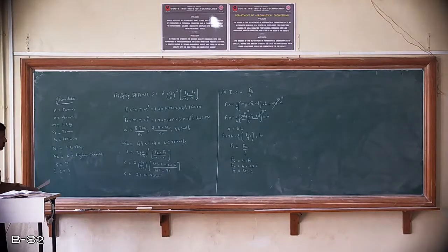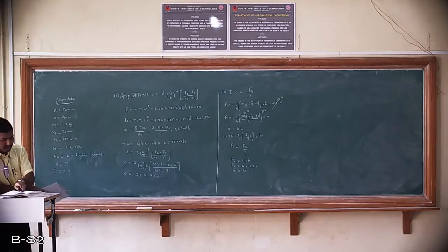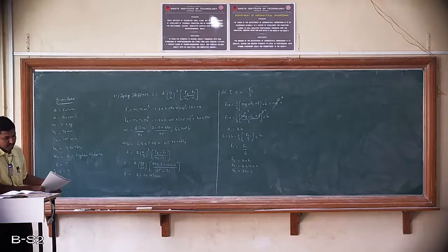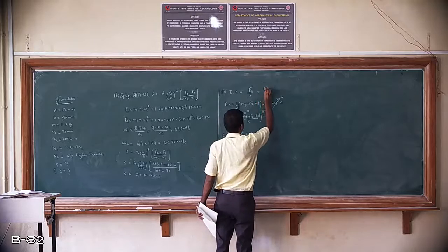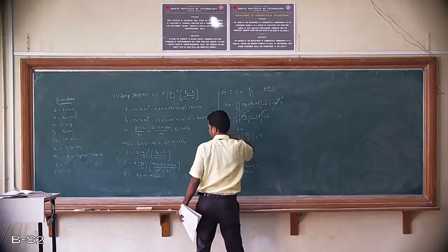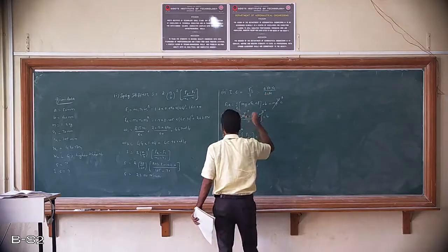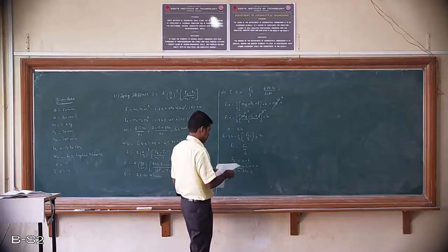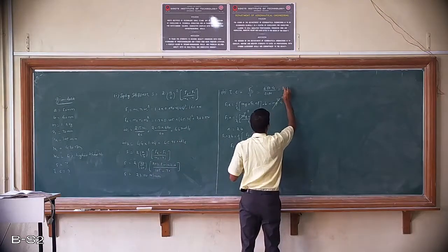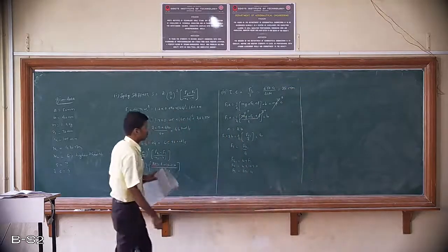So I can calculate the value for initial compression. Substitute all the values here. Fs1 is 650.4 divided by the value of S calculated, that is 23.14, and you get the value for initial compression as 28.1 mm. So this completes the second question for the second problem.